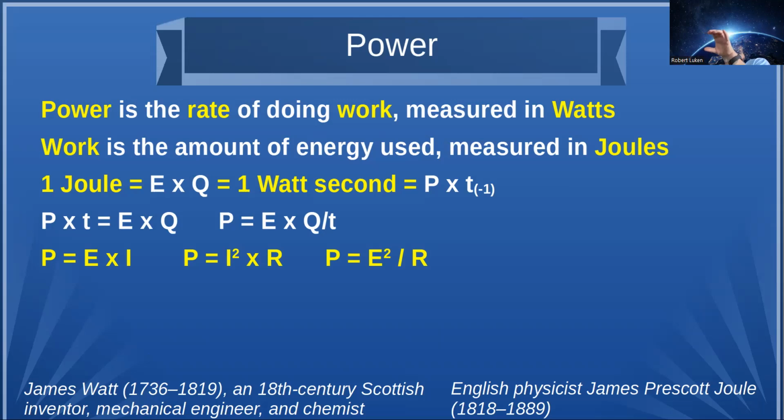because the coax looks like a network of inductors and shunt capacitors all along it. So as long as that piece of coax is terminated in its characteristic impedance, like 50 ohms, and it's driven from a 50 ohm source, then you're going to have essentially maximum power transfer through it. You won't have any standing waves or any reflections.